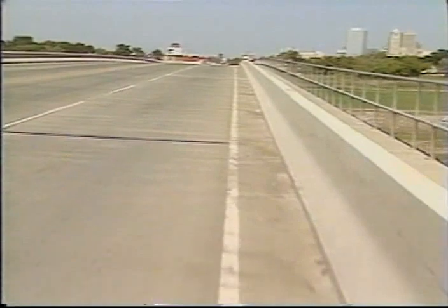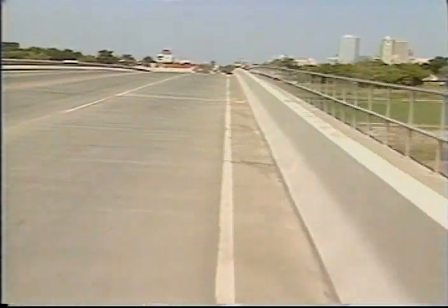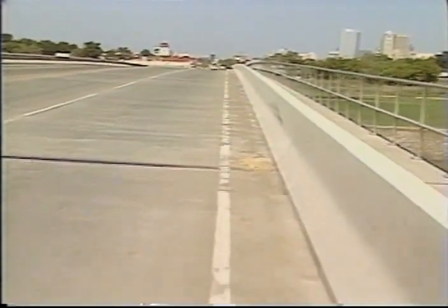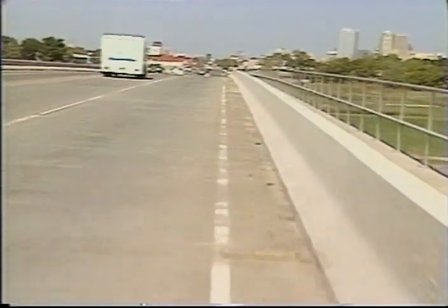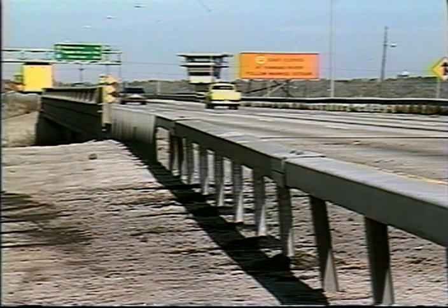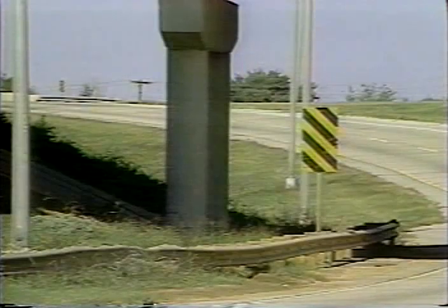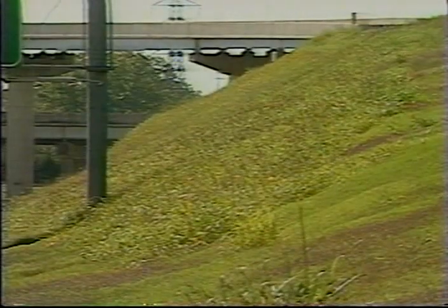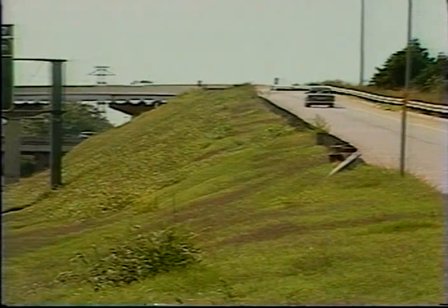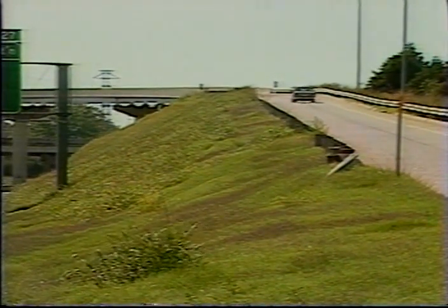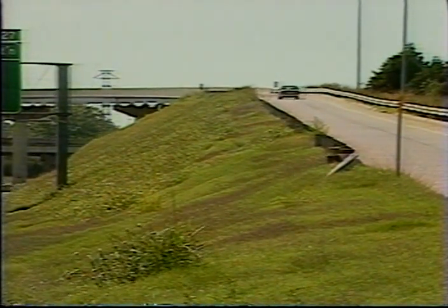These factors can change quickly along the roadway, so the type of barrier selected generally fits the prevailing kinds of hazards and their locations, as well as the kinds of vehicles using the road. Obviously, the kind of hazard will largely determine the type of system selected to provide the necessary protection. For example, the barrier required for a rigid bridge pier would be different from one needed for a steep embankment. The barrier must be capable of retaining, decelerating, and redirecting a vehicle in such a way that no serious injury or death occurs to the passengers.